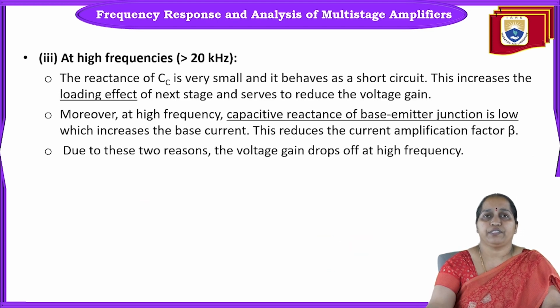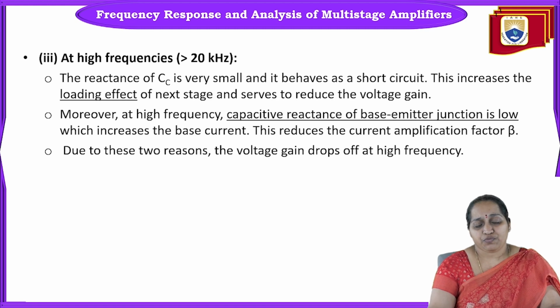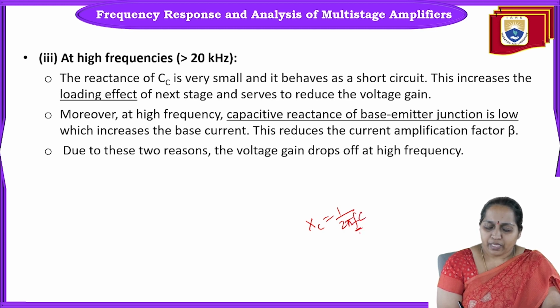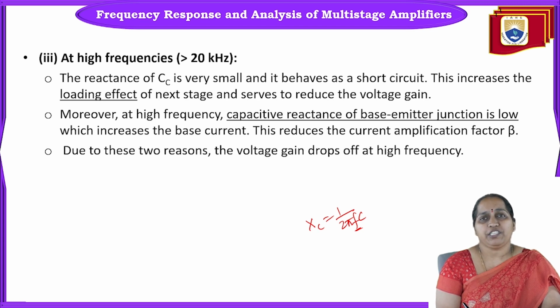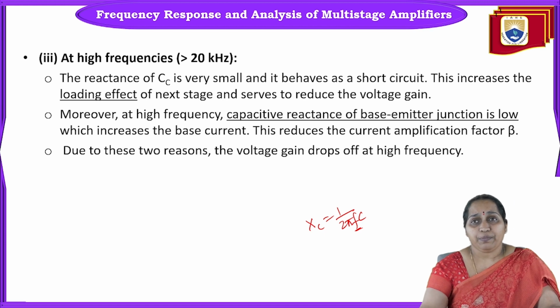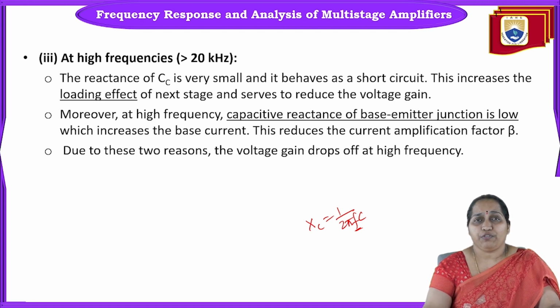Then at higher frequencies, at very high frequencies, what happens? At very high frequencies, Xc will be very less. The reactance offered by the coupling capacitor is very less. Very less means, in other words, we can simply replace that coupling capacitor by a short circuit. When you are replacing the coupling capacitor by a short circuit, what will happen?